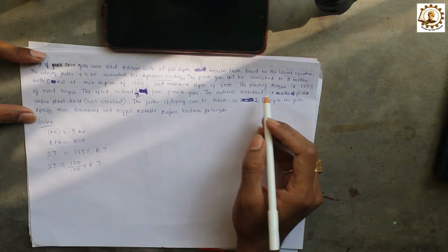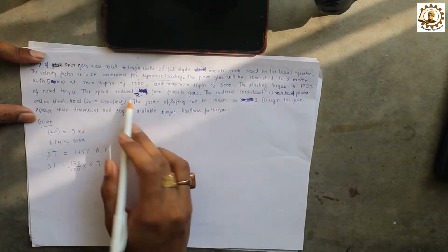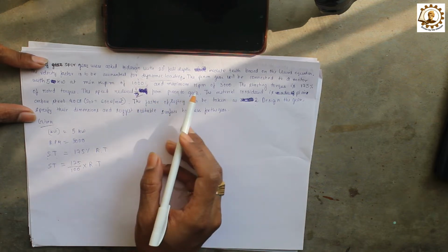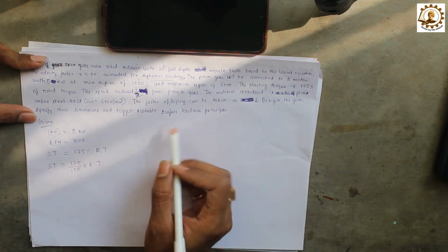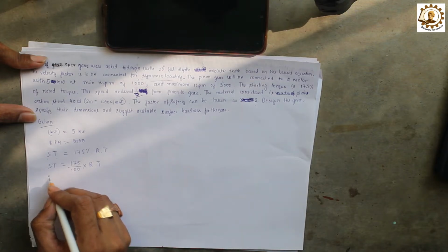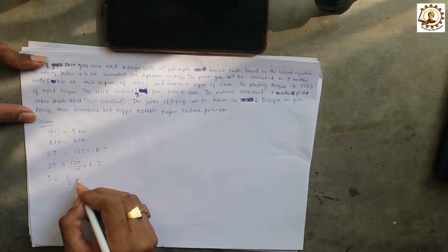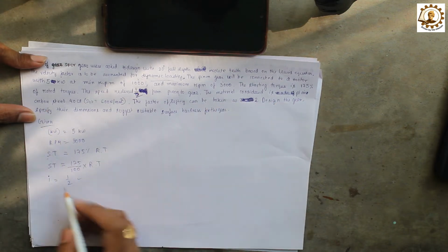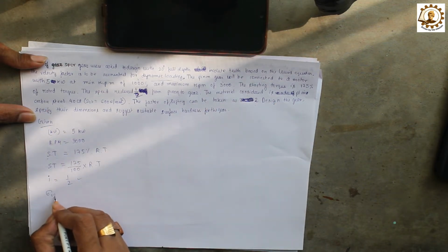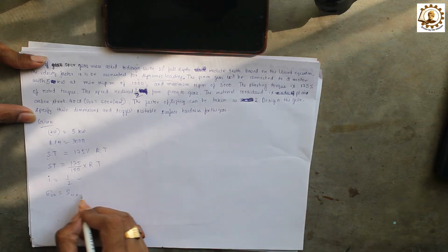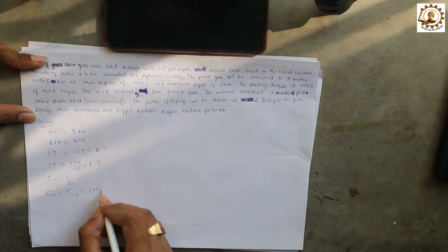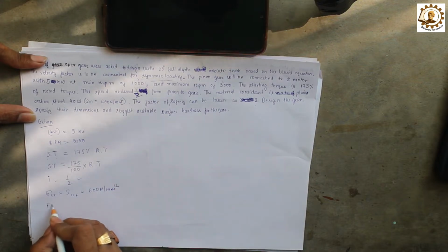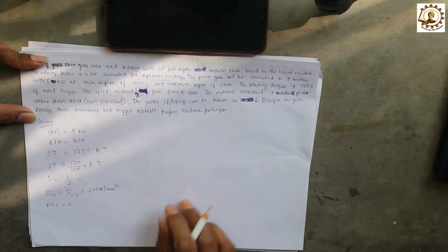We know the rated torque, as well as the speed. The speed is reduced to half from pinion, that is, I equals half. I'll tell you about this one. The material considered, plain carbon steel, has sigma UT or SUT equal to 600 Newton per millimeter square. The factor of safety is equal to 2.